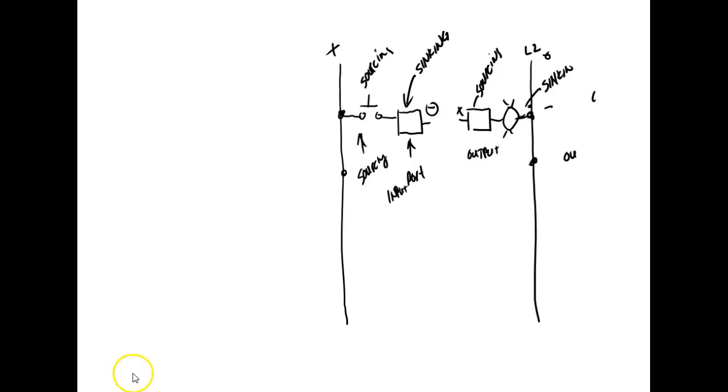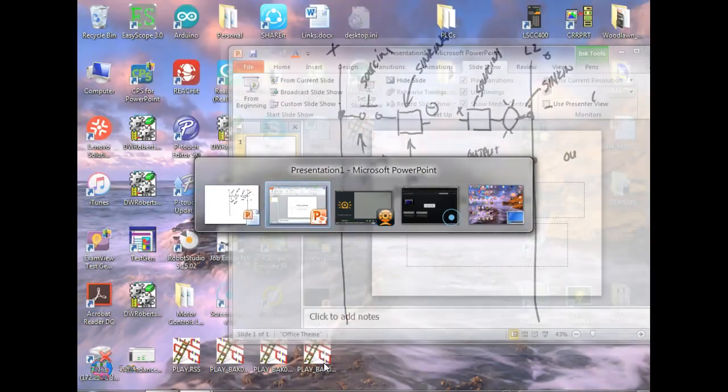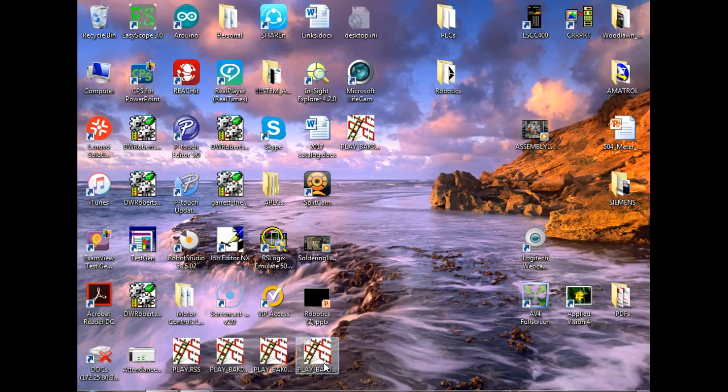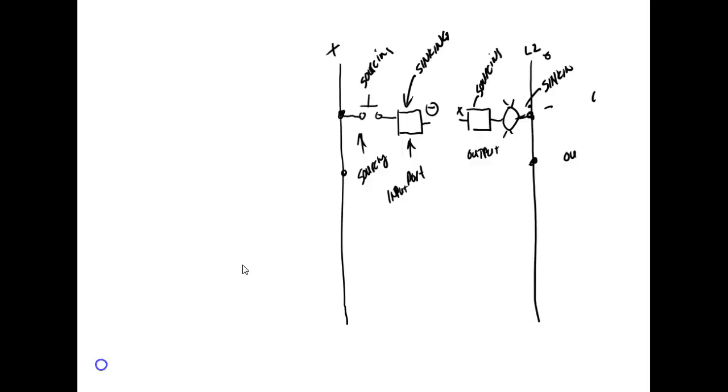Now, these PLCs, the 1100, allow me to decide. So when I come over here and look at, y'all can come on up. So sourcing and syncing only comes into play with DC. If I've got AC input modules, you don't care, right?